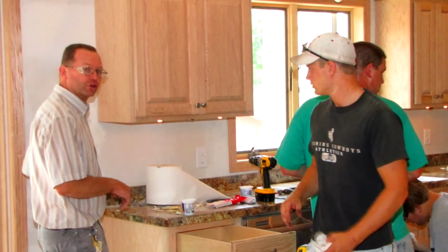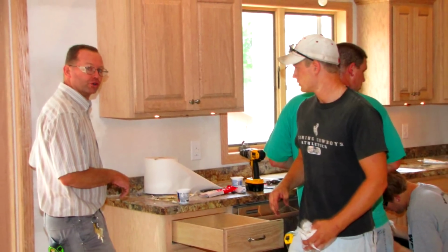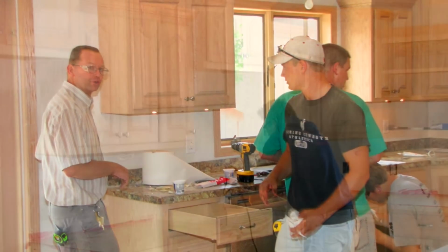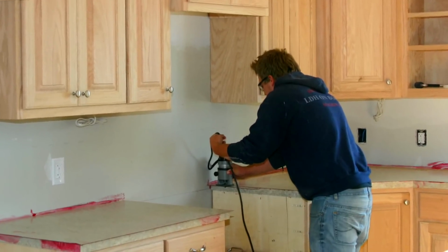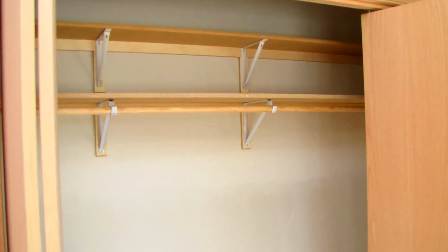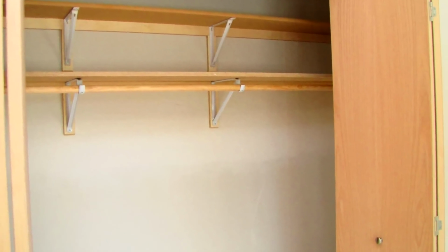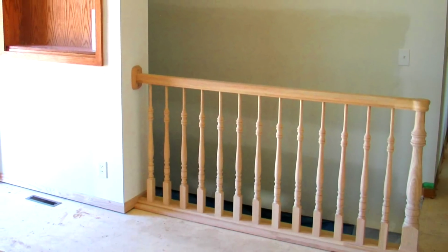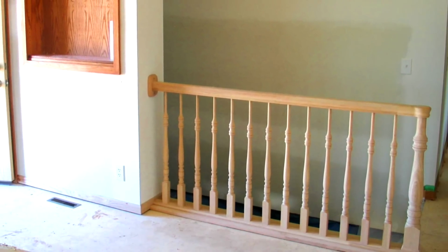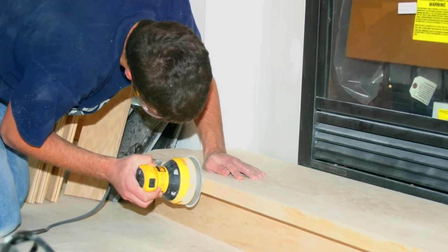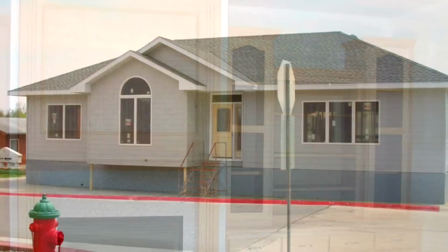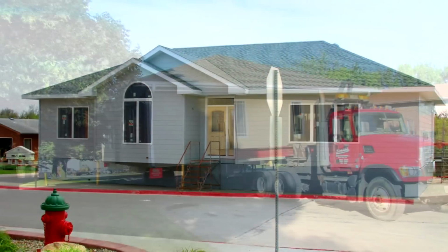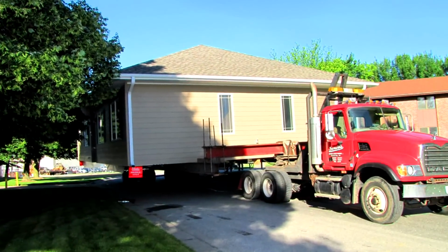During the drywalling process, building construction students construct all of the interior cabinets that will go into the new home. When the drywall process is completed, students begin to install interior doors, kitchen and bathroom cabinets, and countertops. Students complete the door casing, window casing, and baseboard throughout the home, followed by handrails, fireplace surrounds, and other finishing touches that are required in preparation for the sale of the house. The construction knowledge students gain through the house building process is an invaluable experience in preparing for a career in